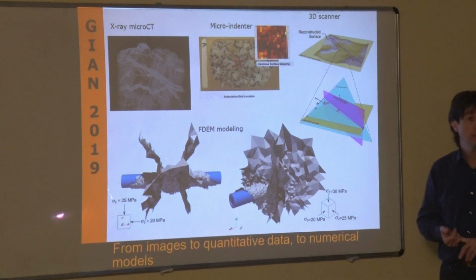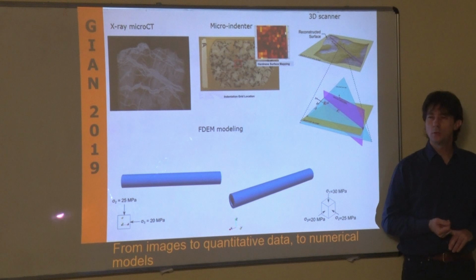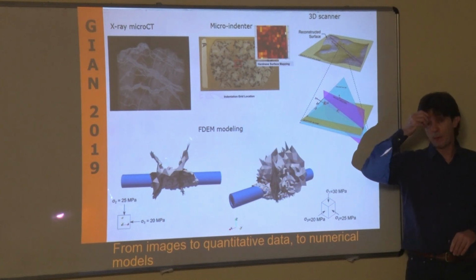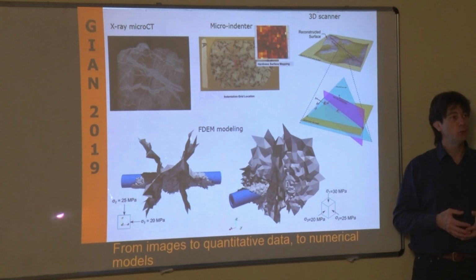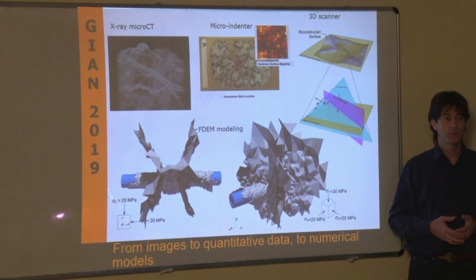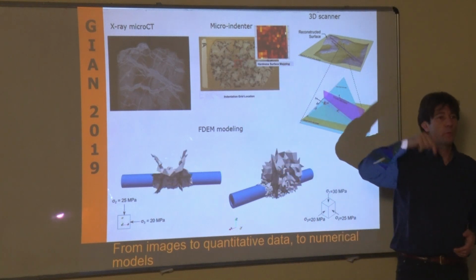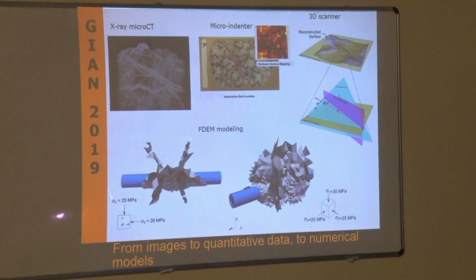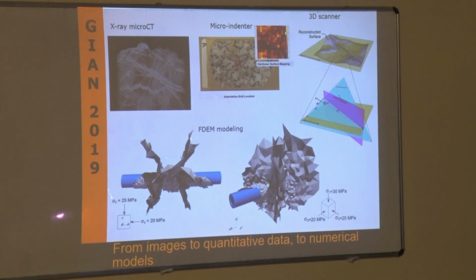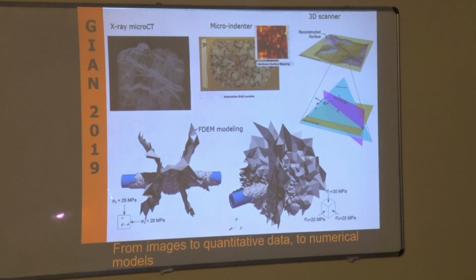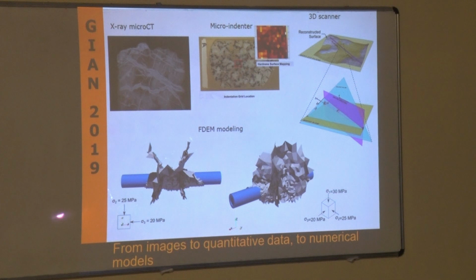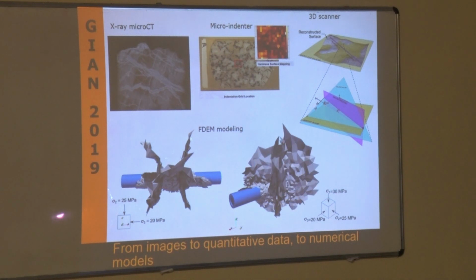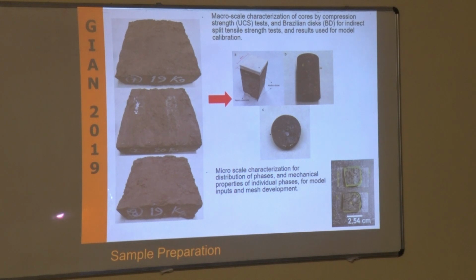And one way exists actually, and it's called indentation. You saw the indenter in the lab here. That is a classic macroscopic indenter. You can actually make it small, and you can start probing your material at the single grain scale. So now you don't have anymore the elastic modulus of your sample, but you are going to have a distribution of Young's modulus associated with the single grains. That may be what you want to start using, and of course to characterize the material at a larger scale.